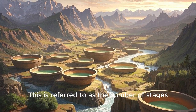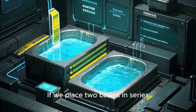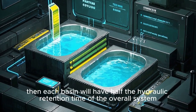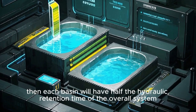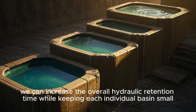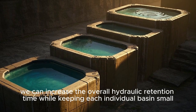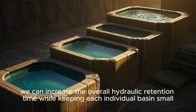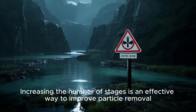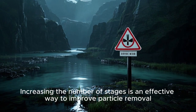This is referred to as the number of stages. If we place 2 basins in series, then each basin will have half the hydraulic retention time of the overall system. And by adding more basins in series, we can increase the overall hydraulic retention time while keeping each individual basin small. Increasing the number of stages is an effective way to improve particle removal.